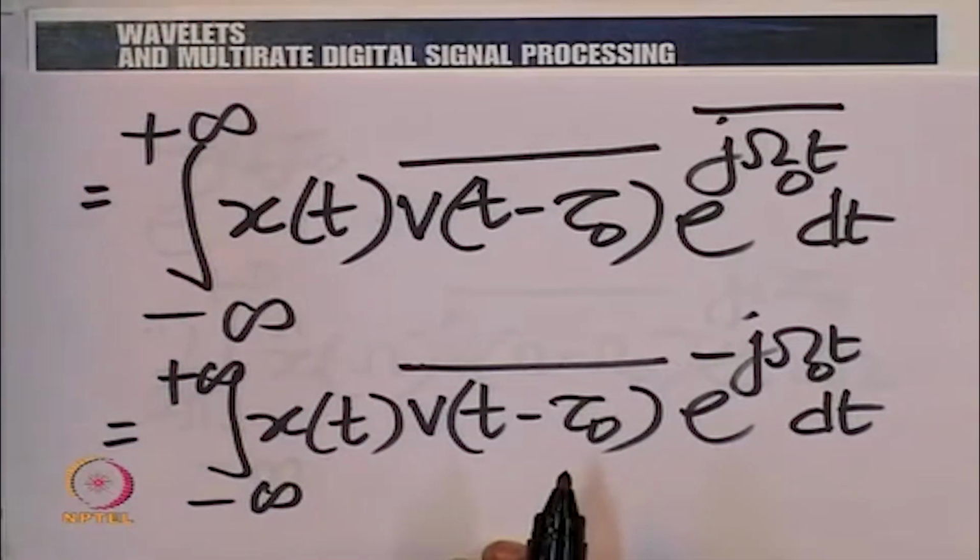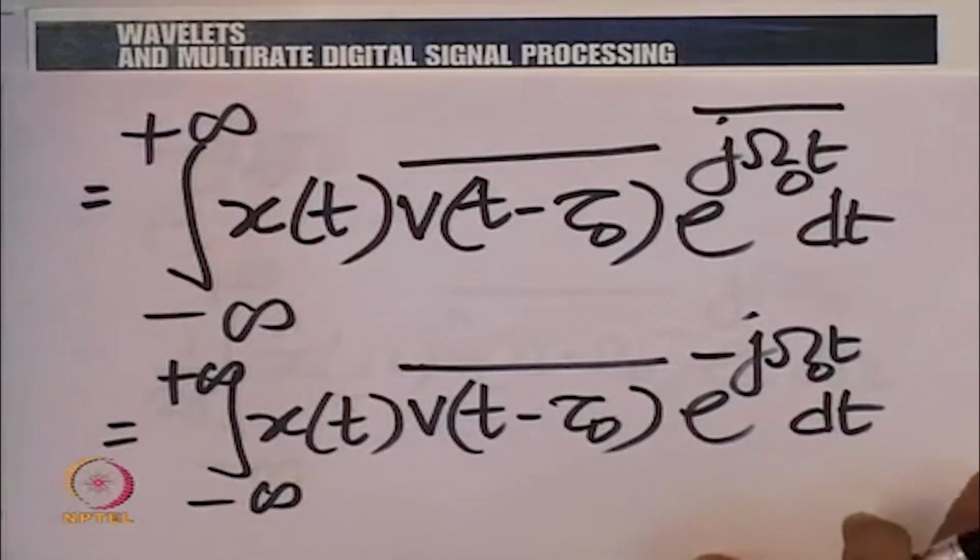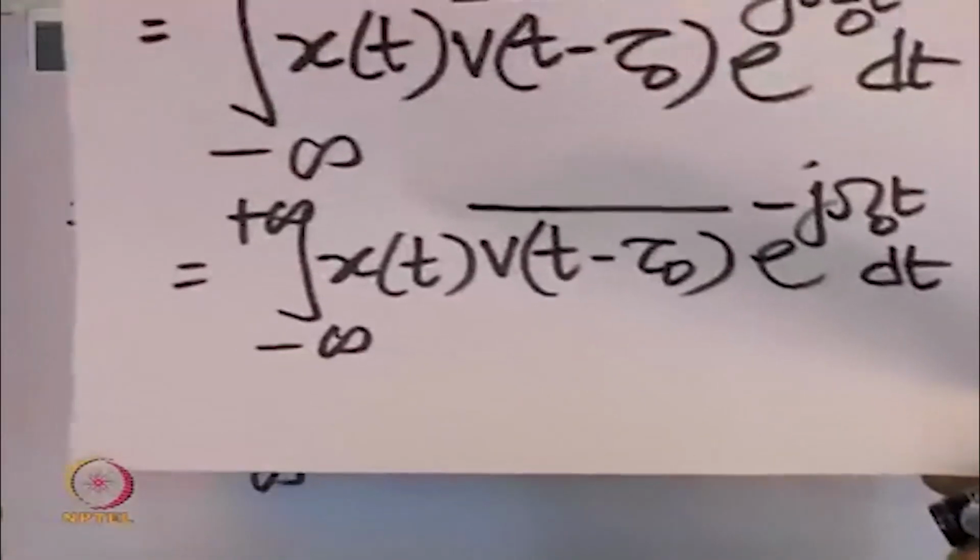This completes the beauty of duality in the interpretation. We are doing exactly the dual of what we have done in time in frequency. That is what we have said. The operation is very similar in time and frequency. It extracts a region of time, and it also simultaneously extracts a region of frequency. So, in a certain sense, the short time Fourier transform was a very good idea when it came, although when they used the rectangular window it was a bad idea, and the rectangular window was not sufficient for that reason. You had to taper off the window at both ends to make the function continuous.